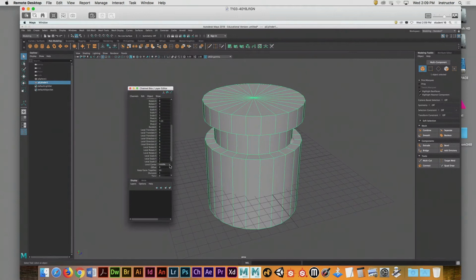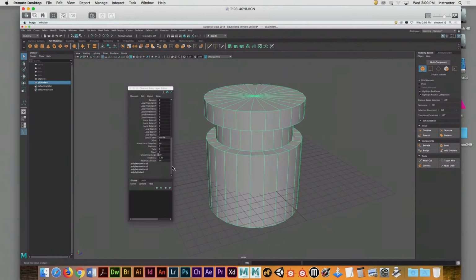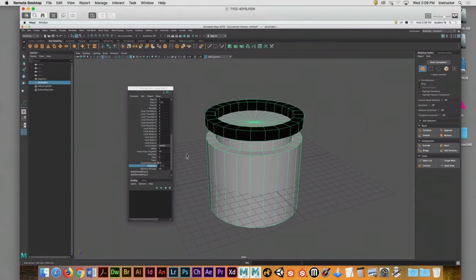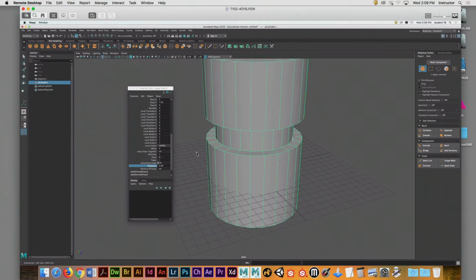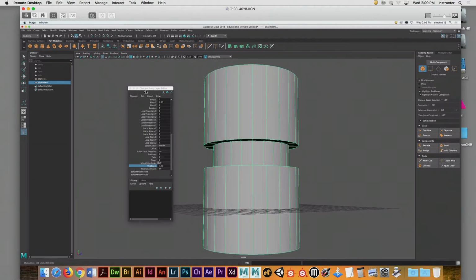Now, in all honesty, the shape creation nodes don't do a whole lot for us. But it is nice to be able to go back in on a poly extrude or a bevel and have access to all the channels that were used to fundamentally do that operation. I've done that all on bevels before. Go back in and resize the offset to adjust the chamfer or the bevel settings. It's pretty cool. Okay, I went the wrong way. There we go. So now I'm changing the thickness on that top bevel, and I'm continuing to make some changes.